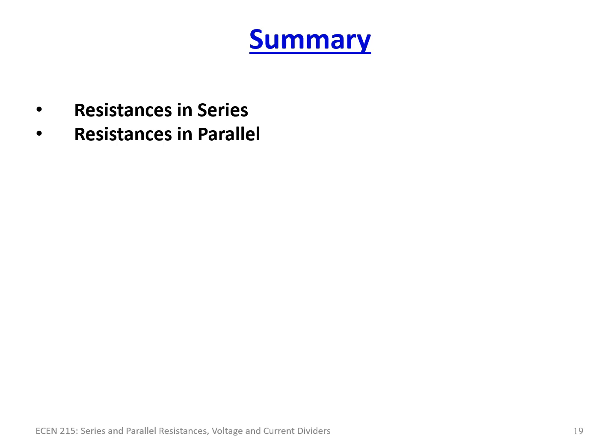Another trick to remember on parallel resistors, if you have X number of parallel resistors that are all the same value, then the equivalent resistance is equal to the resistance given divided by X, or N, the number of resistors you have. So if you have two 50 ohm resistors in a parallel configuration, the equivalent resistance is 25 ohms. If you have 4 100 ohm resistors in parallel, then it's just 100 divided by 4, or 25 ohms.